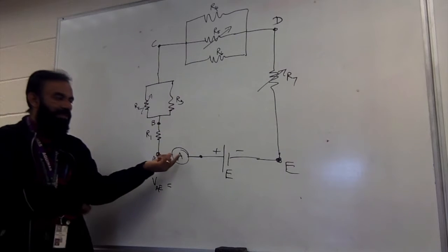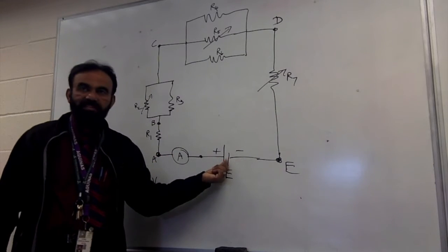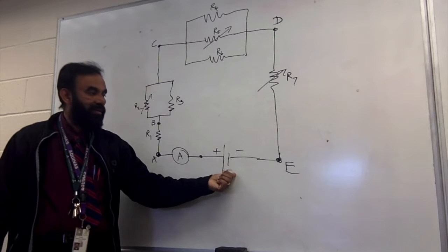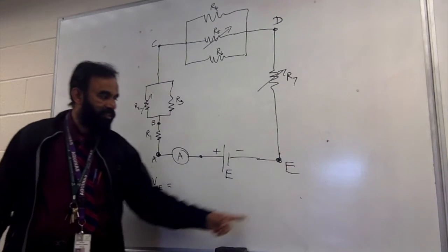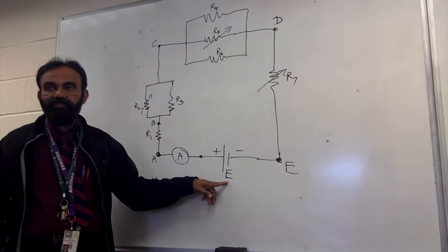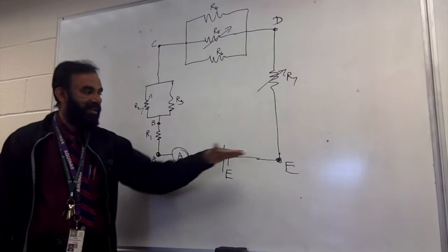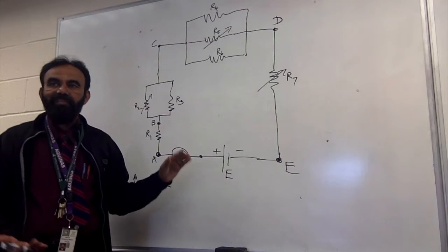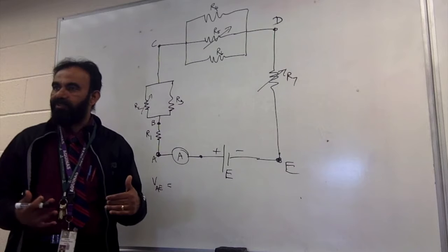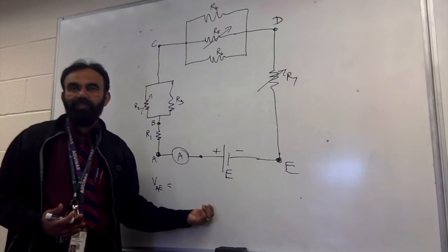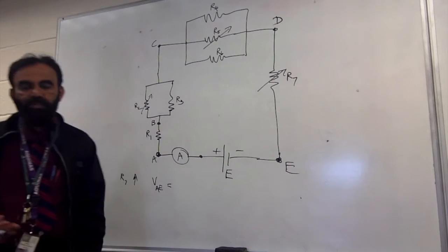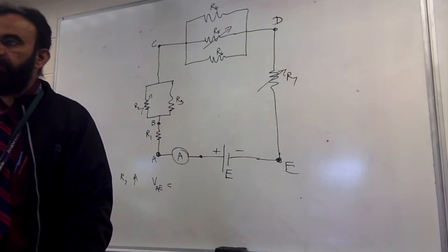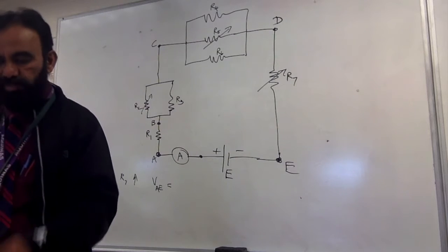Yeah, so what is happening is if this has a resistance and this has a resistance, there is a potential drop created in them. That is why the voltmeter here should read less than the EMF. But now when you increase the resistance, the current which was making that drop reduced, and therefore the drop reduced also. So you are expecting to get a higher voltage here. Make sense? So when the internal drop reduces, the external drop becomes higher. Simple as that.